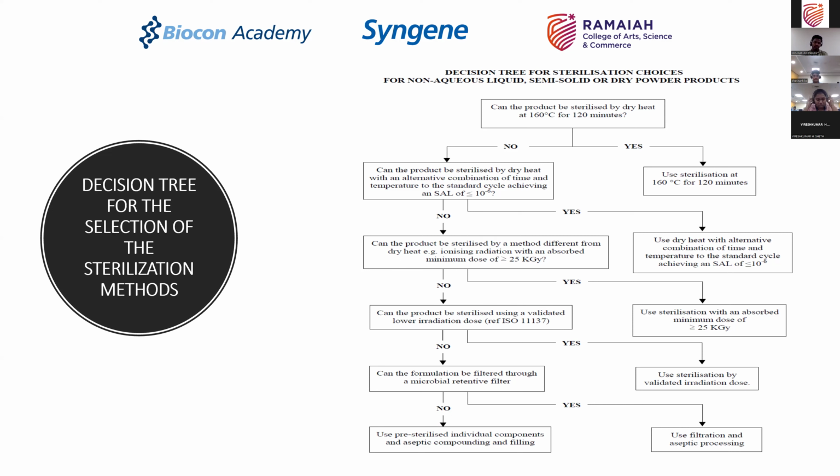I would combine the first two steps of this decision making tree as a variant of each other, because you are still using dry heat as a sterilization technique. In one, you are defining a precondition of 160 degrees centigrade and 120 minutes. And in the other one, you are tweaking that cycle to still be able to do dry heat sterilization. So for me, this condition here and here, which is a decision-making tree, are one and the same, because ultimately you are ending up with a dry heat sterilization at a given condition to achieve a 10 to the power of -6 kill rate, right?